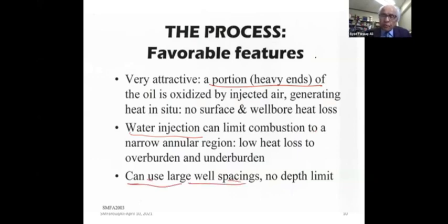So in in-situ combustion, if you have these wells here, this is a producer, and this is an injection well. So I'm showing you a plan view. This is the plan, and this is a 5-spot pattern. And so if you're doing a steam injection, the pattern size, which is the area in the pattern, will be of the order of 5 acres, which is about 2 hectares.